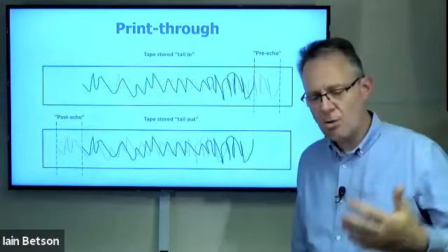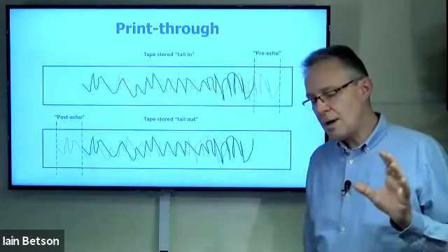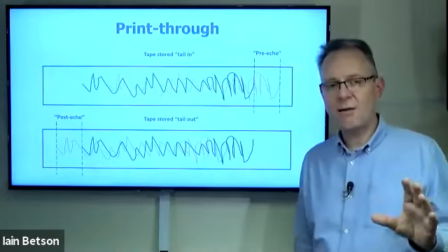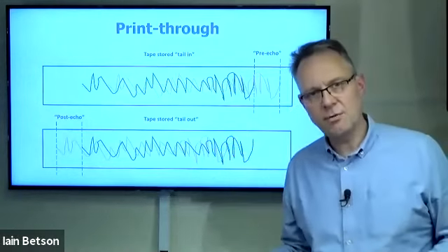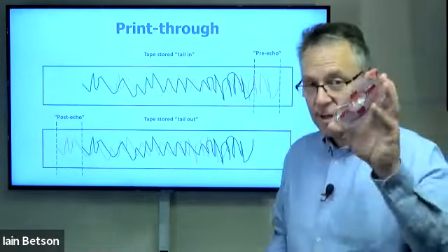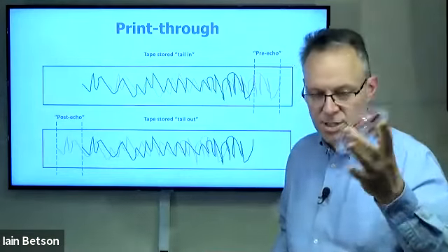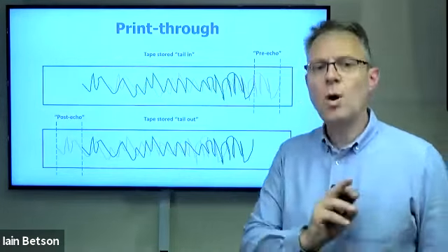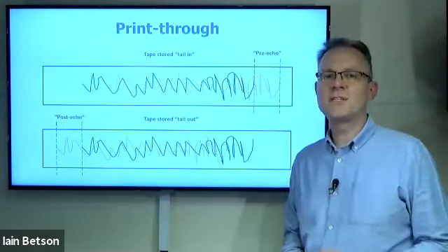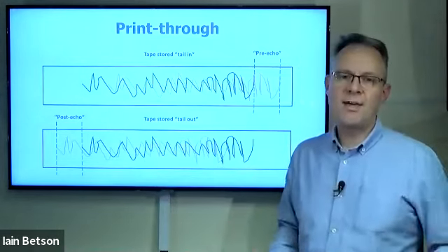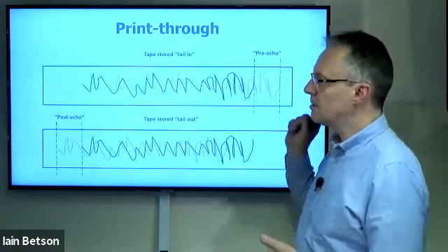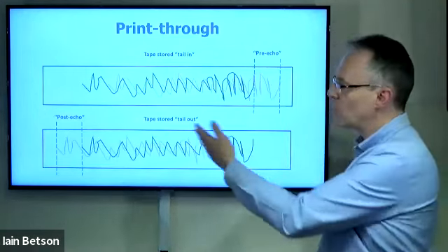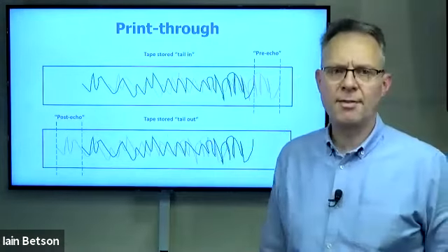explained, and I hope that gets over that if you store your tape in a tail out fashion, i.e. you have to load the tape on the right hand side, the take up reel first, and indeed if you put your coloured leader tape on, you'll know which end is which. You then have to rewind it before playing for the first time onto the take up spool, and then you can play it. Hopefully you'll minimize the effects of print through because it will be post echo rather than pre-echo.